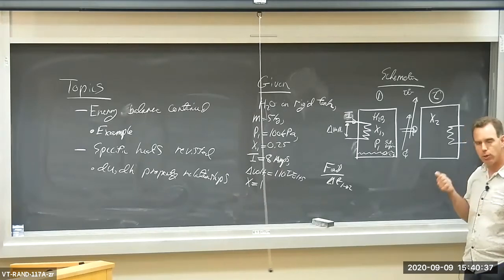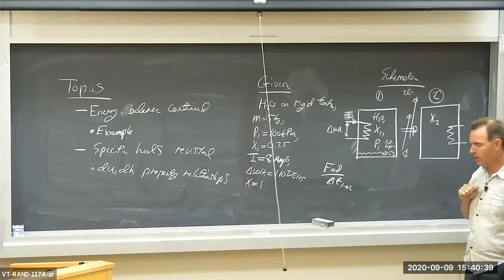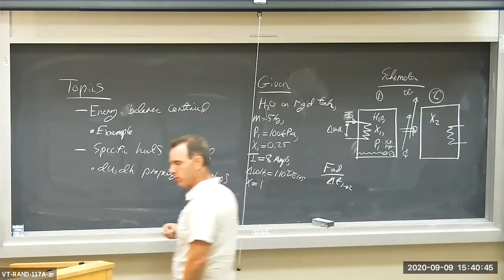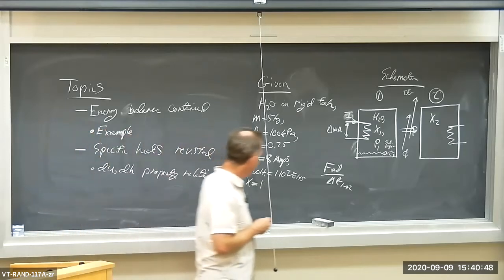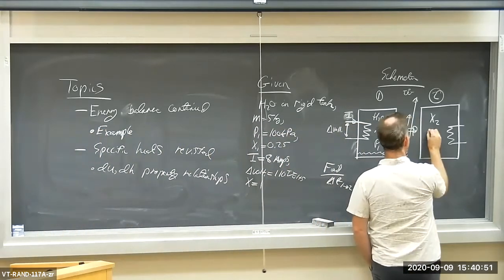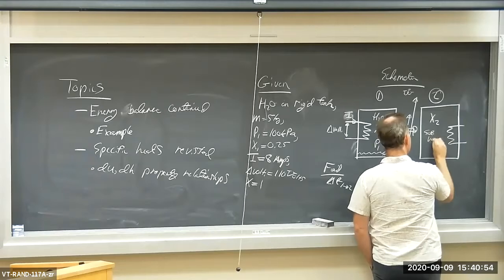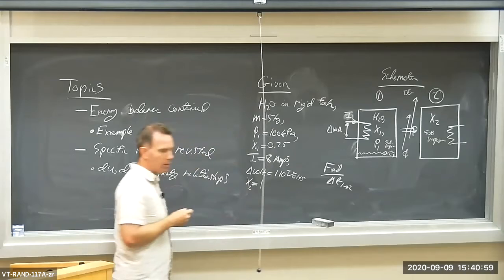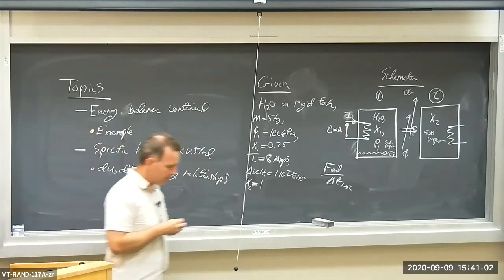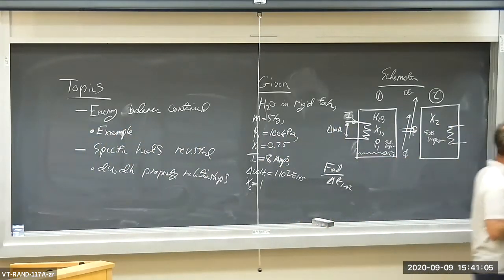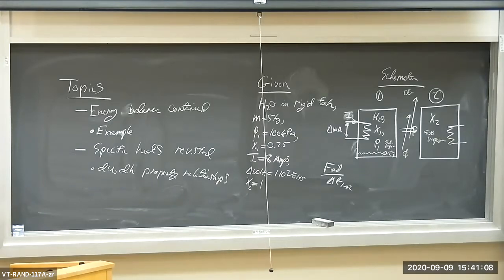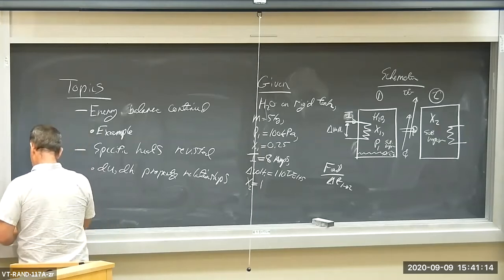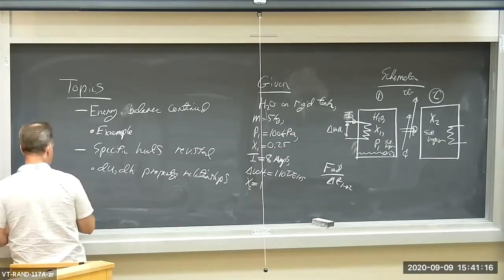So this rigid container initially contains a mixture of H2O, liquid and vapor. The heating element is turned on. We dissipate energy. We heat up the H2O until all of it becomes a saturated vapor. So state 2 is a saturated vapor. So quality at state 2 is equal to 1, all right? So what are we supposed to find? Let's find out how long, delta T, how long it takes to boil away all the liquid and to get a saturated vapor in our rigid container.